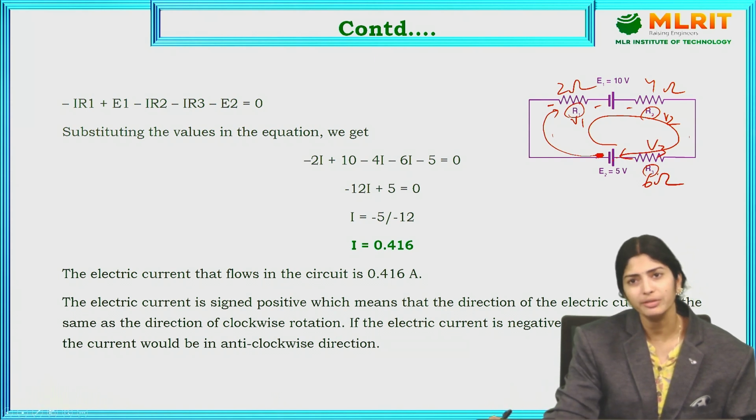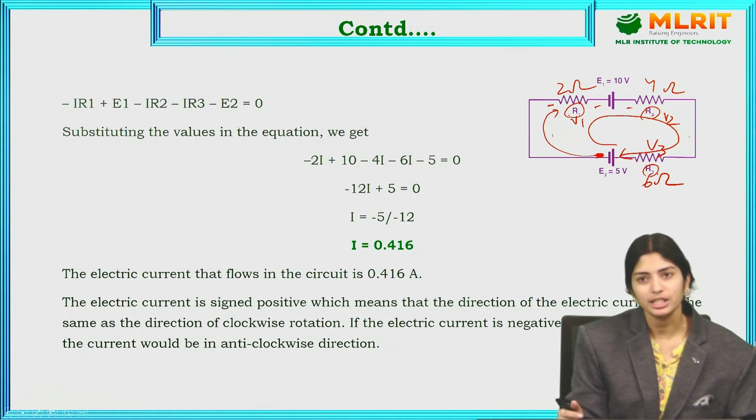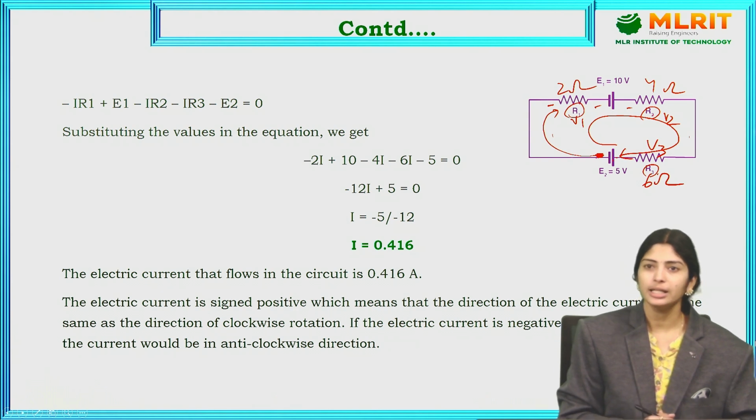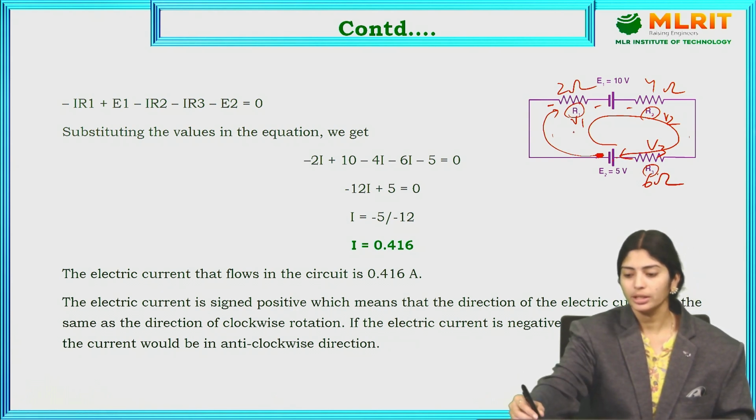Okay, so why will there be a voltage drop across each resistor? While the current is flowing into the circuit, what will happen? What is the property of the resistor? It will oppose the flow of electrons, so some amount of energy will be lost in the form of heat, and there will be some amount of voltage drop. Okay, so that voltage drop here is V1.